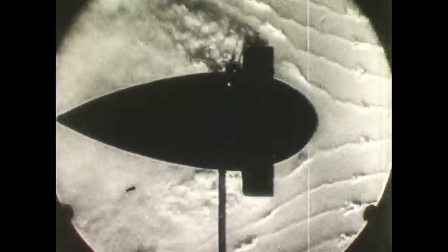But with a radial engine installed, the turbulence and the very wide wake indicate a considerable drag. A ring which conducts air over the cylinders limits the area of turbulence, reduces the wake, and improves performance.